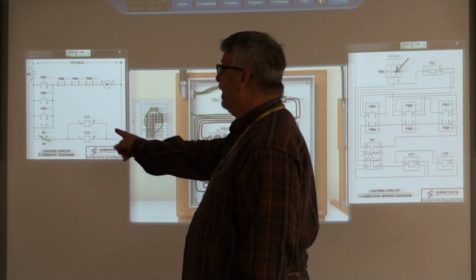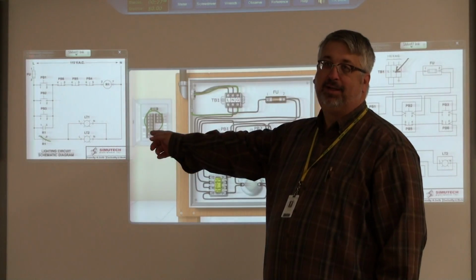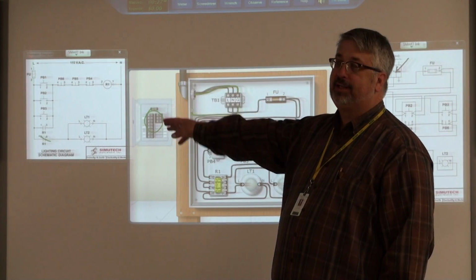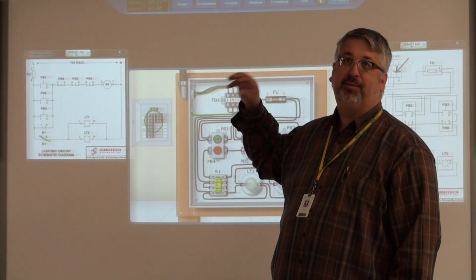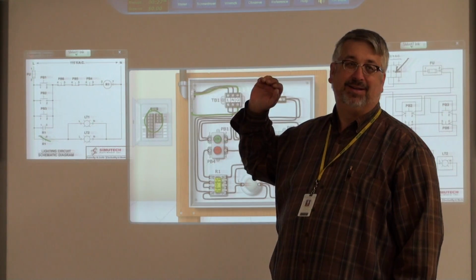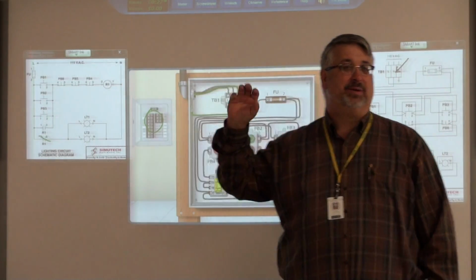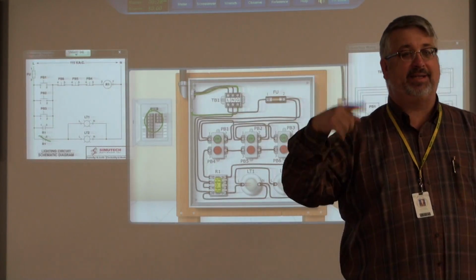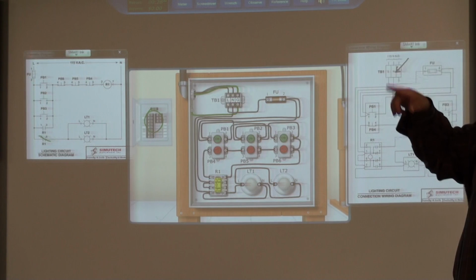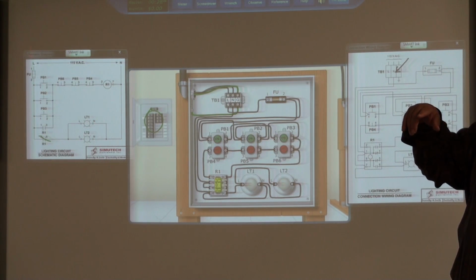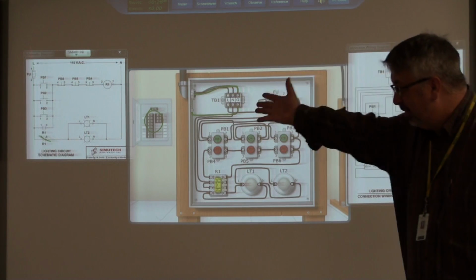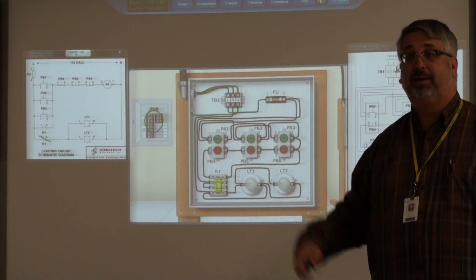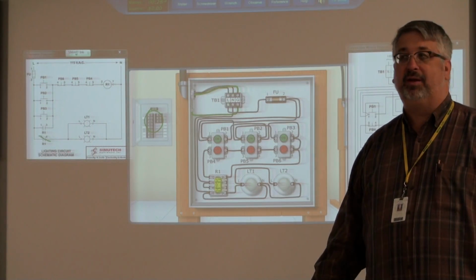So we could actually see the lights on 4, 5, 6, right? So are we correct that we'd see the lights stay on, but we'd be able to watch the relay coil change state when we press the buttons? That's true. So we just learned a new symptom. Think back to some of the weird things you went through with the simulator, going, how can it be on, not on, and the lights are on? Now you know at least one thing. There's probably a few others, but there's one.